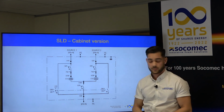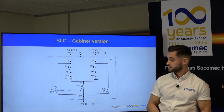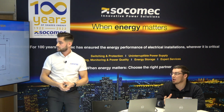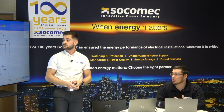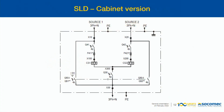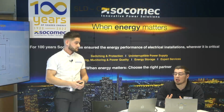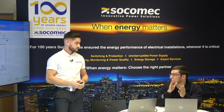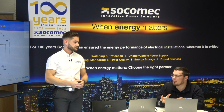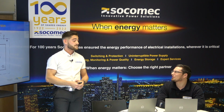Yeah, it's interesting. The Q50 switch there, it is the 3 positions, so you can't accidentally switch it the wrong way and drop the load. What it does do is it monitors as well as you're turning it. So if you were trying to turn to source 2 bypass, but you accidentally switched over to source 1 bypass by mistake, the switch is monitored, and the static switch will perform a transfer before it goes into bypass. So you've sort of got a bit of human error redundancy there, if you like.